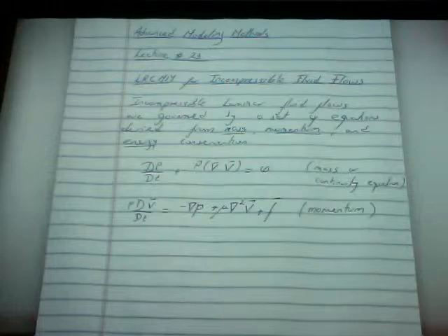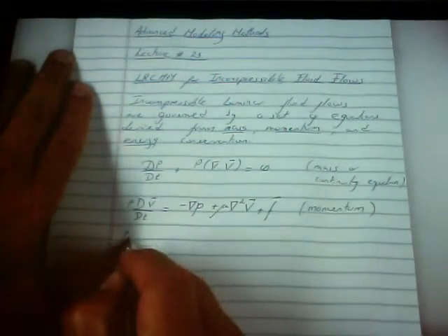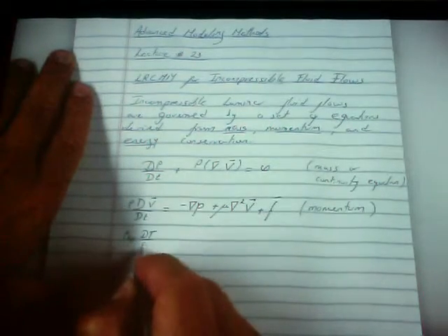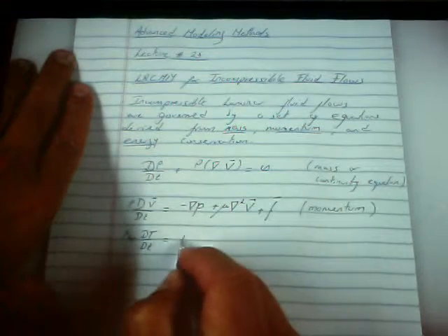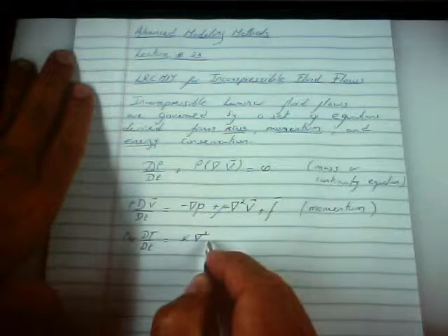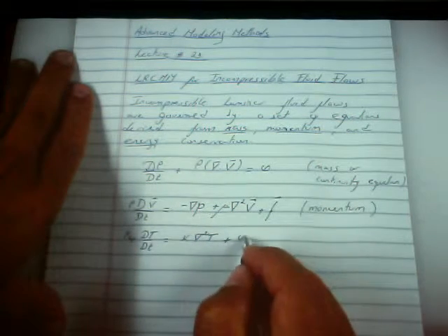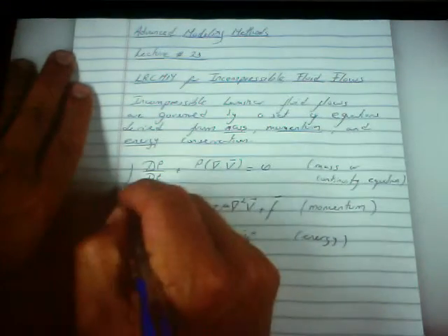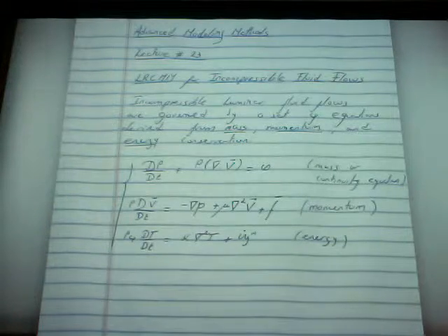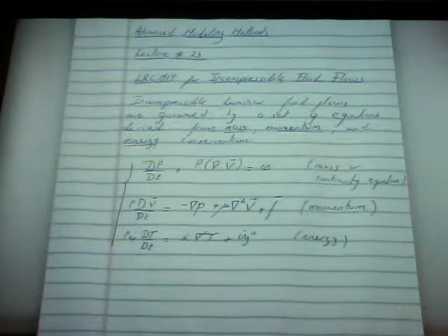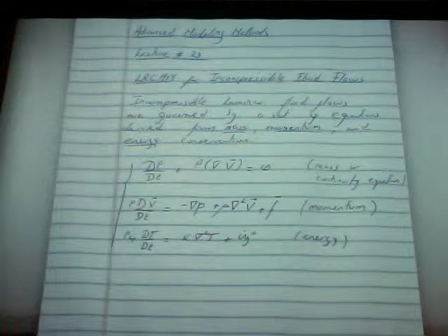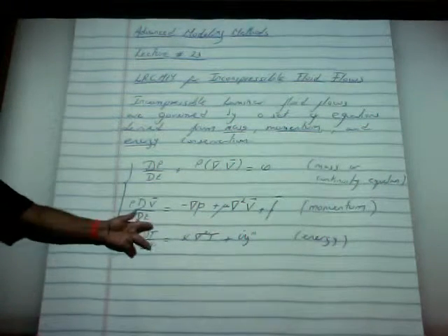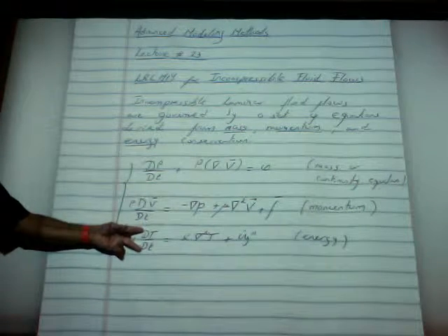Okay? And then the last equation we already saw is ρ Cp DT/Dt is equal to K Laplacian of T, plus q triple prime. This is the energy equation. And that's the first law of thermodynamics, essentially, right? Conservation of energy, now expressed in terms of the parameters of the flow, the temperature. So this is the equation we tried to solve last class, or last lecture.